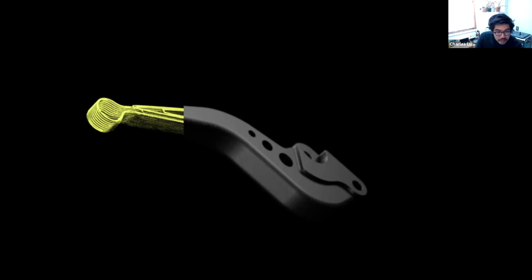Alvin says, I would like to print exhaust shields. Would continuous or chops be best for HSHT? For an exhaust shield, if it's not under any directional loading, the chops might be okay. HSHT reinforcement will get you higher temperature. So see what that does at the exhaust shield.